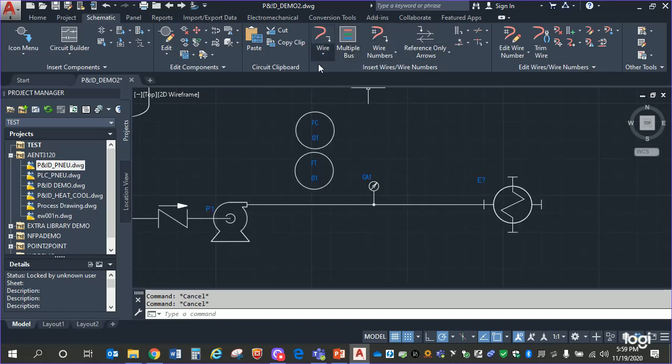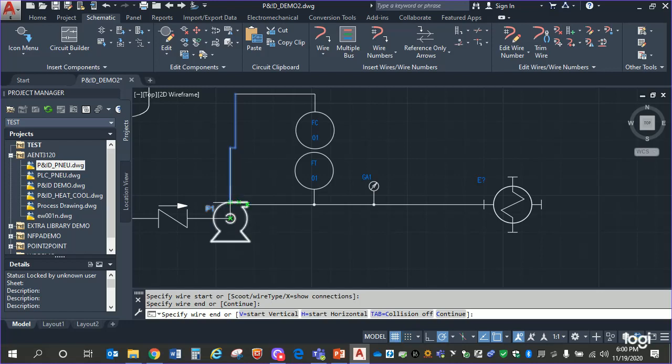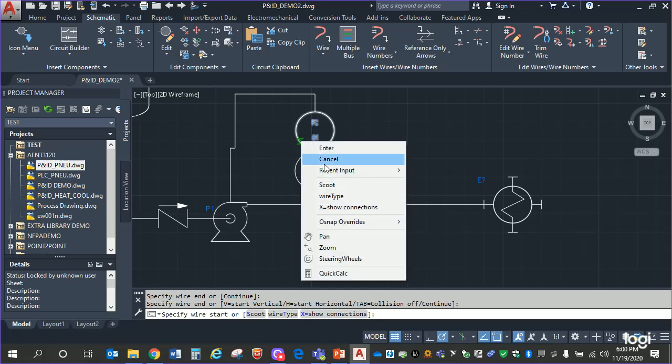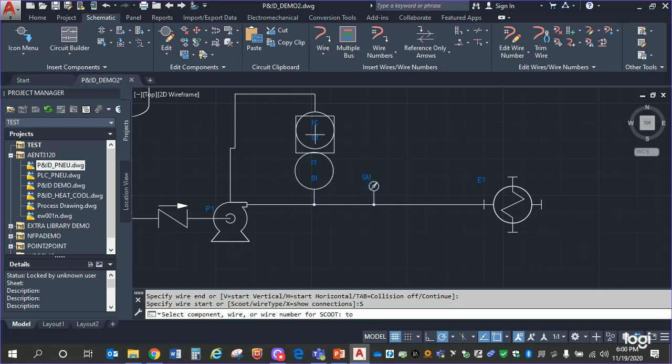And now when I wire this guy up, what I'm going to do is I'm going to go ahead and go like this. From here. I'll go back up. Turn off snap and you get it. Oh, will I? F9. Where's my F9? There we go. And, you know, I really should either pull these apart and put a line in there, or I could even scoot them a little bit down so I could get them a little closer together.